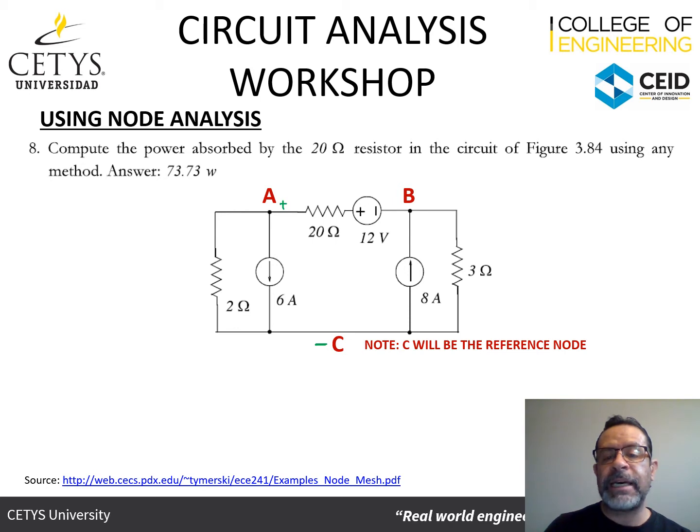And in B, in this case, B from C, B is going to be the positive reference when I'm measuring voltages between nodes. And the other thing is that when we're talking about a reference node, this is equivalent to saying that if I'm measuring a voltage with regards to that node, this point C is the 0. Okay, is the 0.